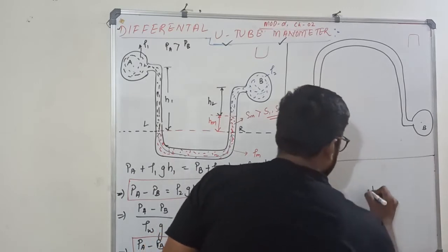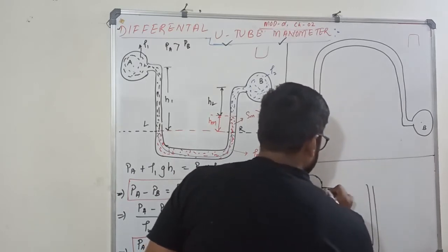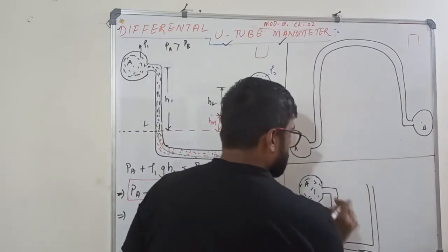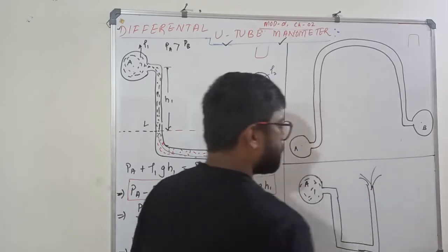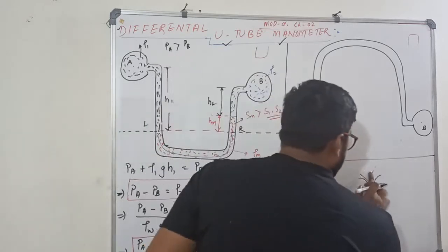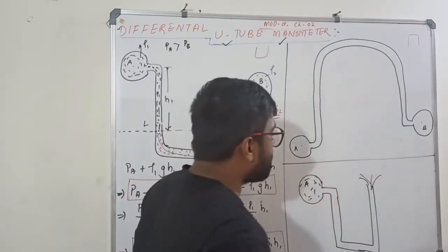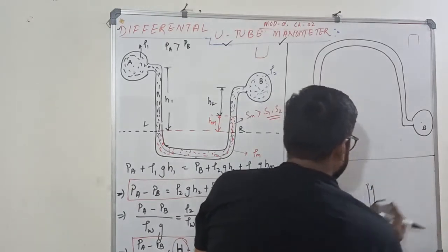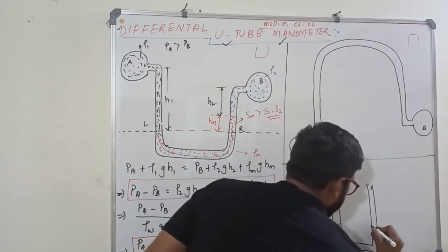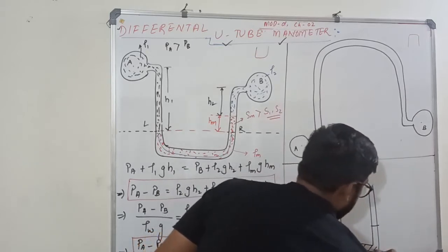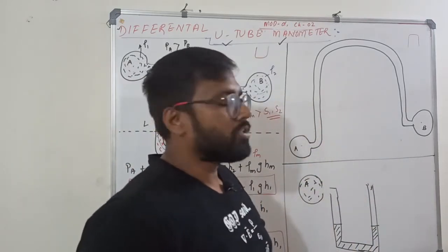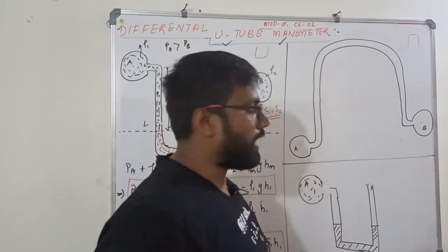Now you go and connect it. If you connect it, what will happen? Whatever the pressure here, it will run through this U-tube and you will get a fountain here. Means the liquid is coming out, so you cannot measure pressure. In order to avoid that, I have not connected it yet, we will use some manometric fluid here. See, it can push air easily, na? Less density. So in order to avoid that, I have used some manometric fluid.